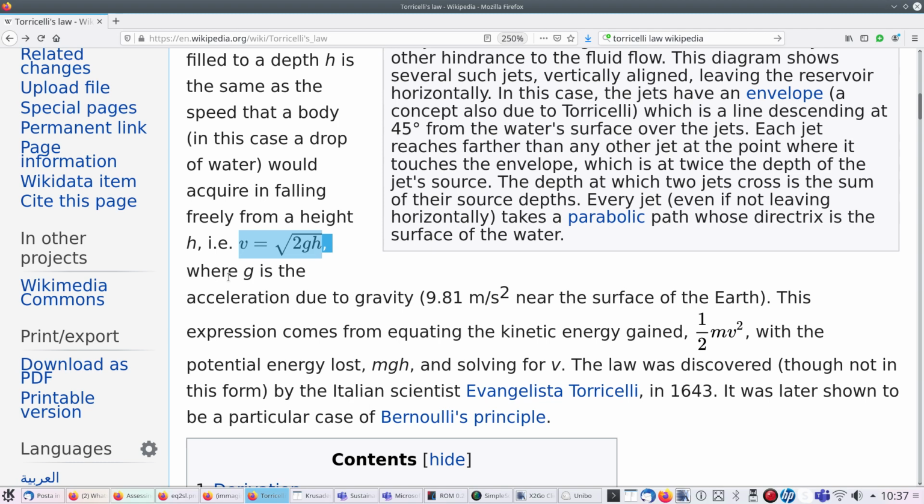We are not now going into the demonstration of this, just keep it for true. Velocity is linearly proportional to flow, which means, by Torricelli's law, that flow is not linearly proportional to storage, is not linearly proportional to h, water level, and therefore not linearly proportional to storage. So physical evidence suggests that the relationship between W and Q is non-linear.